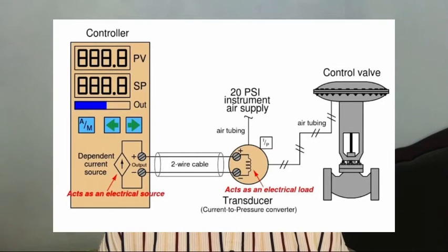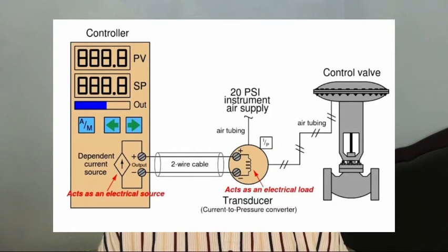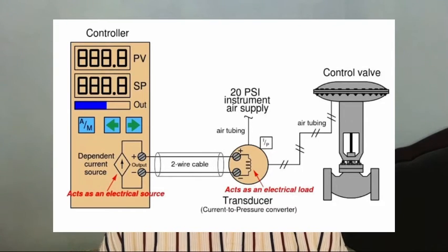One push button provides the operator with a way to switch between automatic and manual modes, or A to M, while two other push buttons provide means to decrement and increment either the set point value in automatic mode or the output value in manual mode.